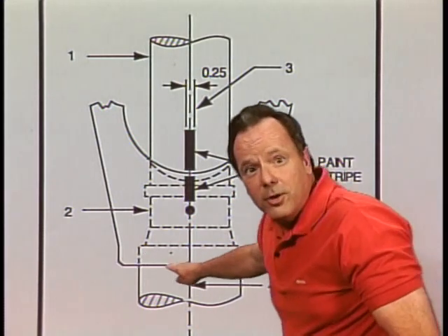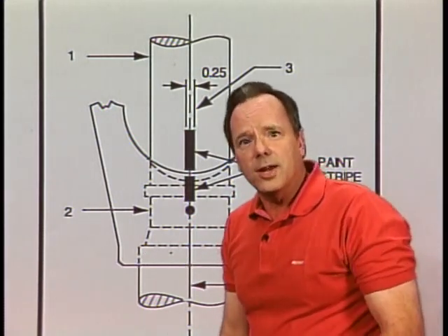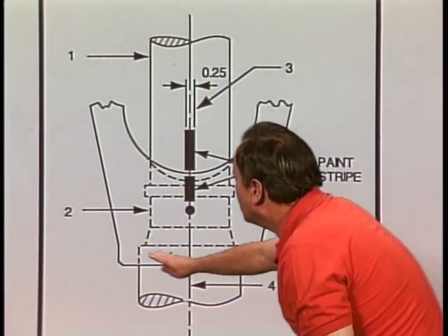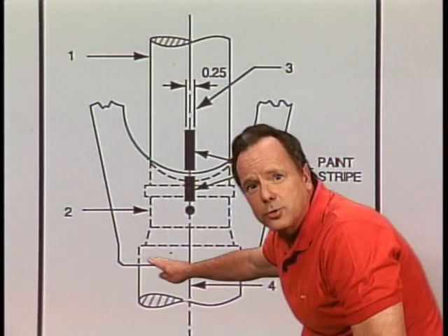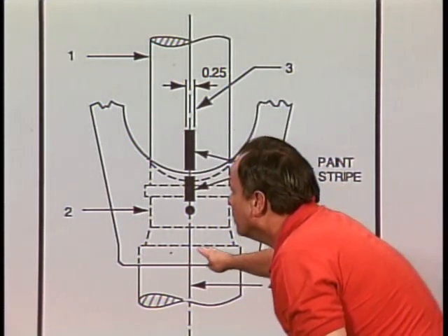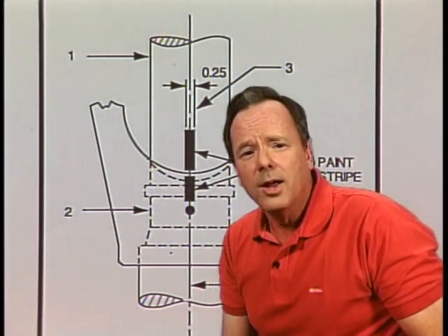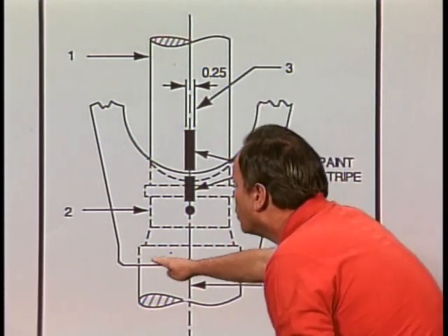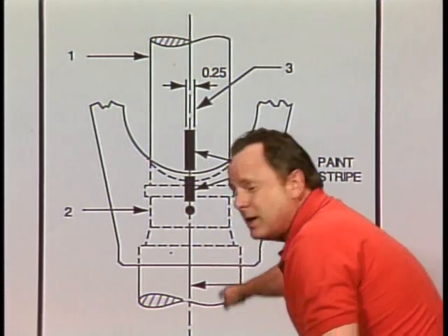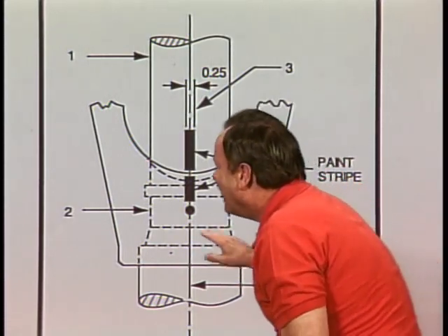The FAA refers to a hidden line as a medium weight dashed line, also known as a hidden line, and it's a type of line normally used in a mechanical drawing like this or a blueprint to represent an edge or an object that would be not visible to the viewer. They call it a series of short dashes evenly spaced. So that's a series of short dashes evenly spaced. That's what it looks like to me, and that is called a hidden line.